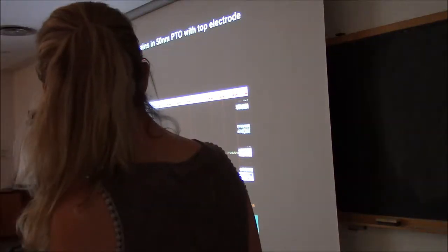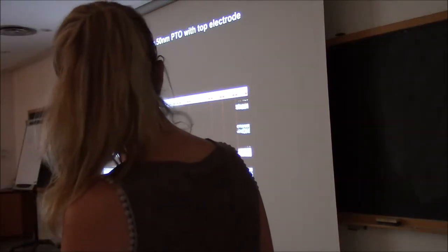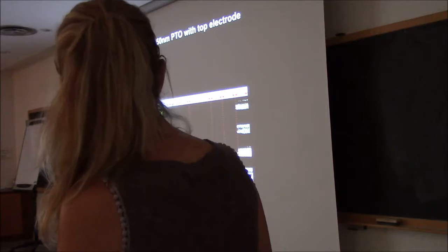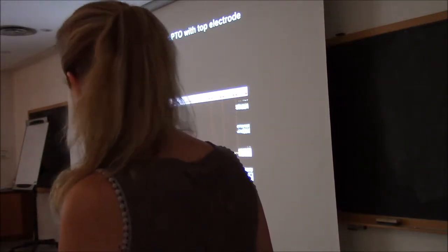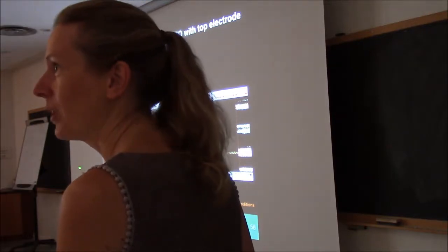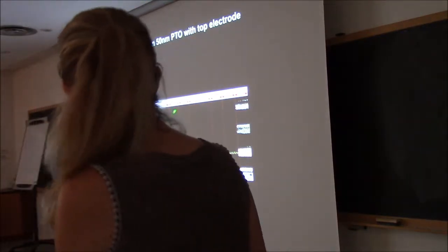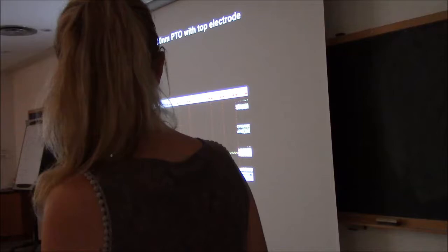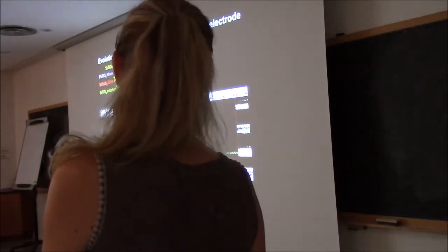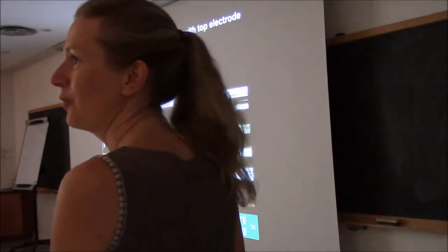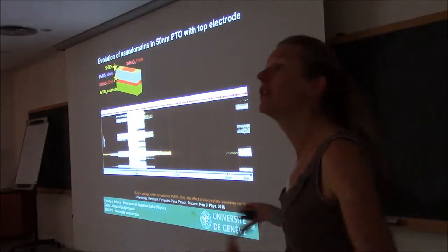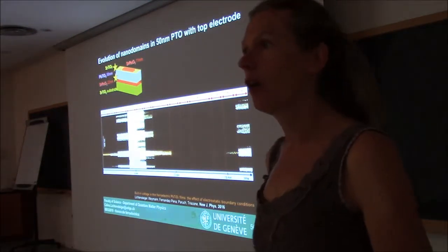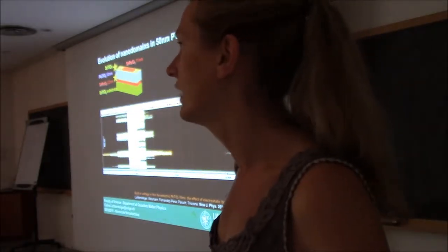And then we decrease the voltage, 1 volt. The other domains appear, 0.5 volts, 0 volt. And here you see the ones that stay longer are the first ones that appeared. And again, we completely switch, so they are completely erased. And we go back up, and you see that the first ones that reappear are the same ones that appeared here. Okay? So again, this tells you that you have some inhomogeneities of the profile of the built-in voltage inside your material.